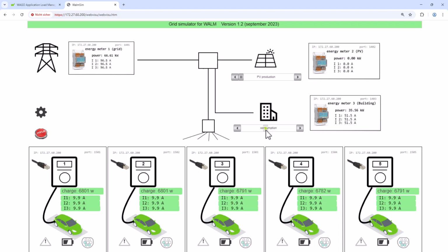at approximately 10 amps. Now let's boost PV output to 30 amps, introducing more available power into our small network, allowing all 5 vehicles to charge at maximum charging capacity, though the main supply current remains at 100 amps. Further increase in PV output reduces the intake at the mains connection point, and with reduced consumption, the intake drops further until we eventually supply power.